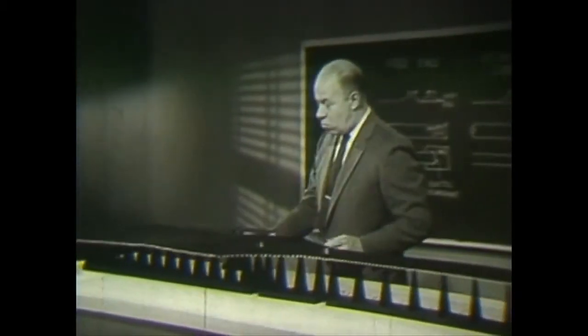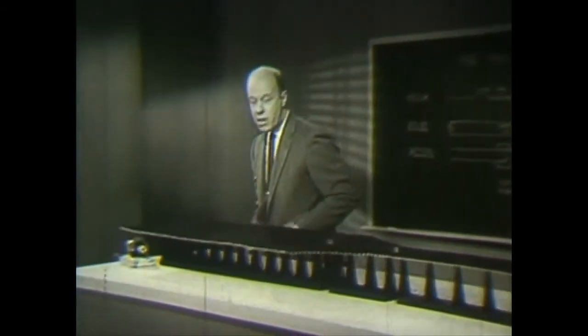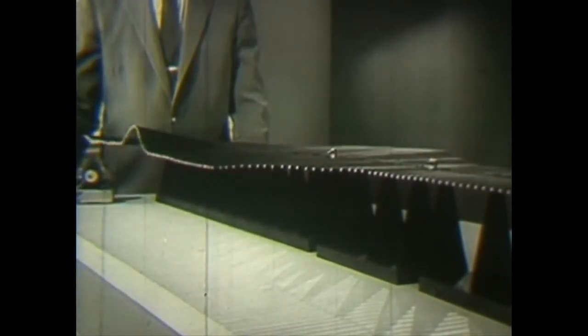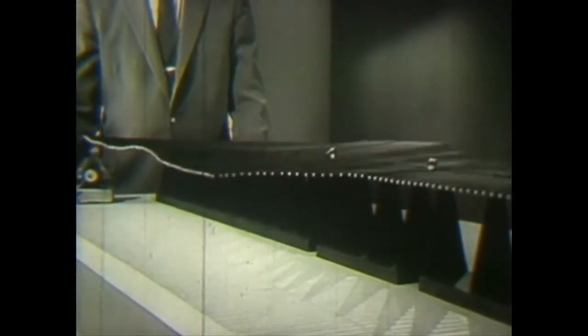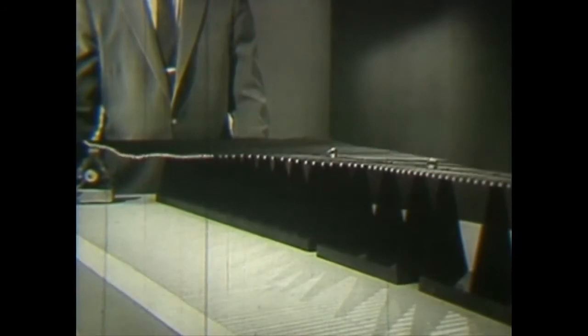It is effective also for use with single waves and pulses. Watch what happens now when I send a number of pulses down this line. Here comes a short, quick one. And you see that hardly any perceptible reflection comes back. Here comes a somewhat longer one. And again, only a small amount of reflection returns. You see, the tapered section transformer is really a relatively broadband device.